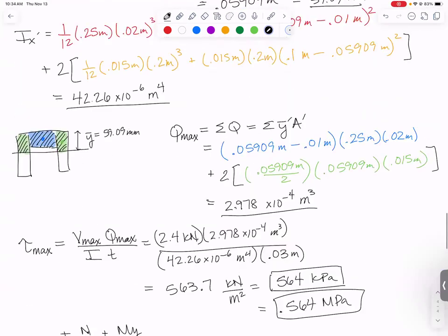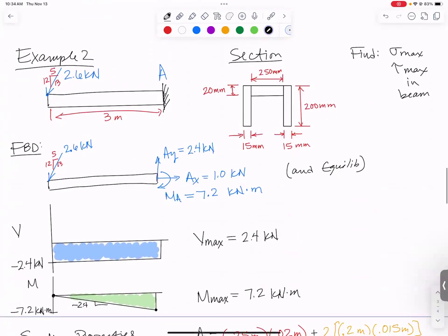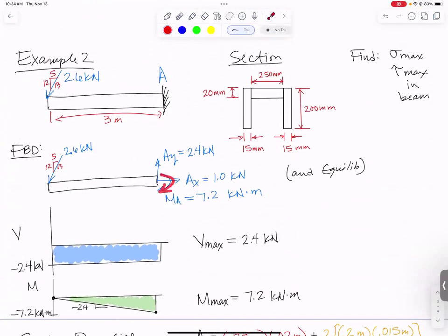Now, which is positive and which is negative? It's essential to get the right answer. Well, let's look at which direction the bending moment acts. The bending moment acts that way. What does that mean? You could think of it this way. We're pushing down on this overall, so it's going to curve downward. In order to do that, you're taking a beam that was straight, and you quite literally have to stretch out the top of it and compress the bottom of it to get that kind of curvature.